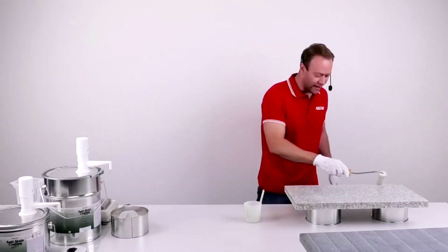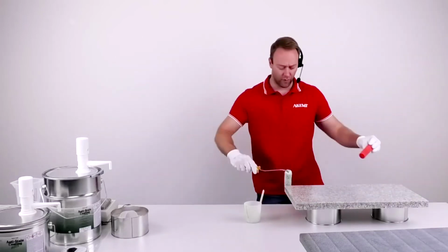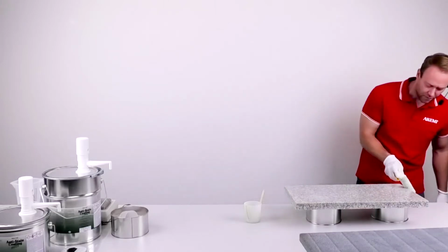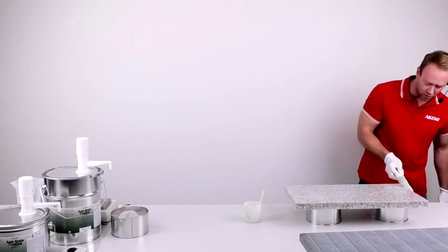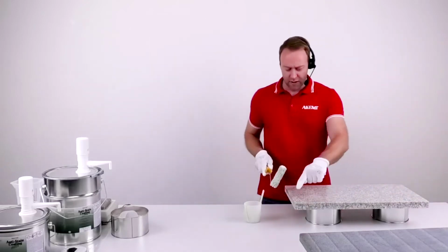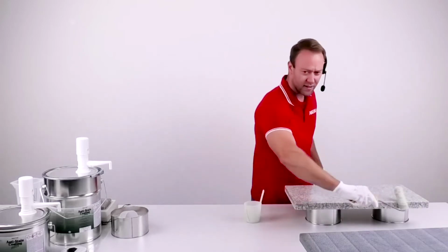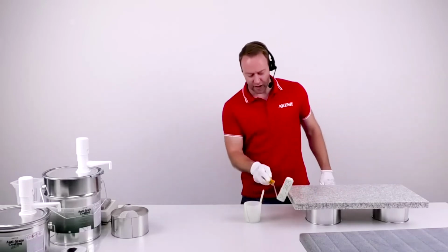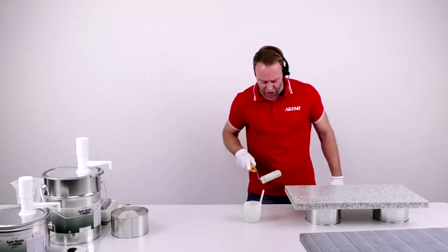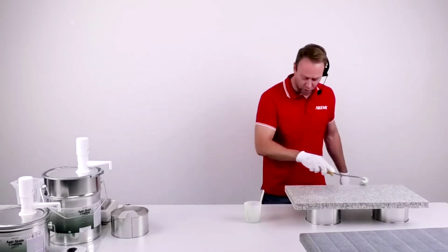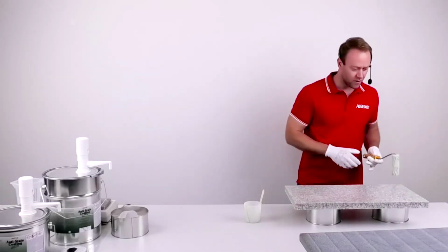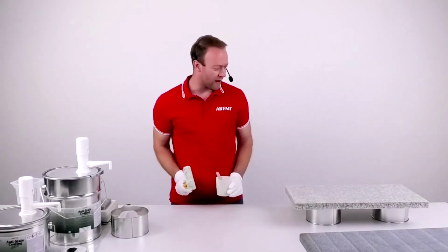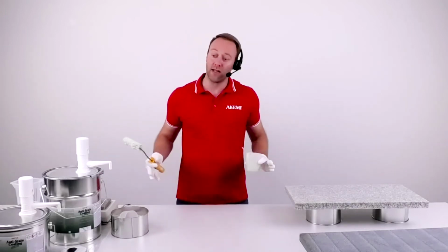What is also important, and here you usually cut the sponge. When you do that for some meters, you cut the edge. That's the reason we recommend the fur roller. Very important is to do one extra line on the direct edge, because this covers the area. There's no use covering the side but forgetting the edge. Otherwise water can go inside here, and we don't want that. So that's one application of anti-stain coating.